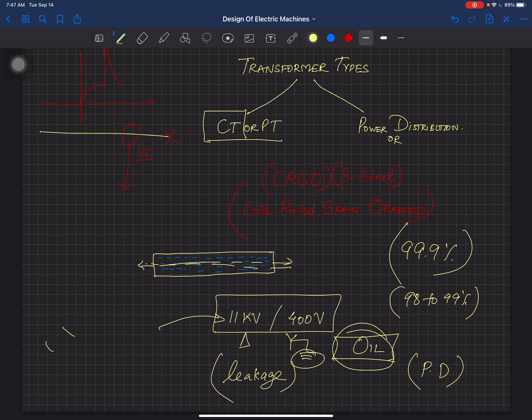So that current is going to give rise to ions, and those ions are actually going to be a problem for you in later stages. A time will come that the transformer dielectric strength, this is a very, very important thing, that the dielectric strength of the insulation, that insulation can be asbestos, paper, mica sheet or whatever, they are actually going to lose their dielectric strength, and they can't withstand this voltage or even a 400 volt voltage.